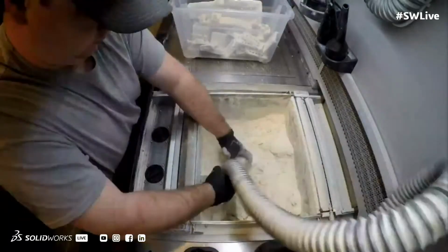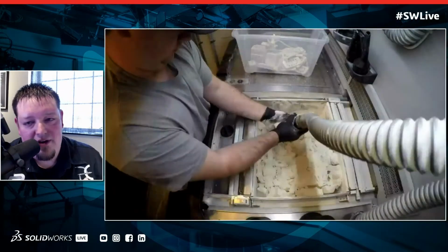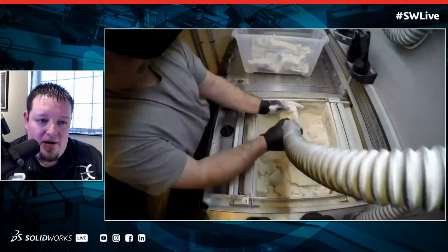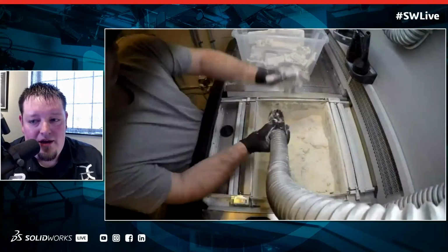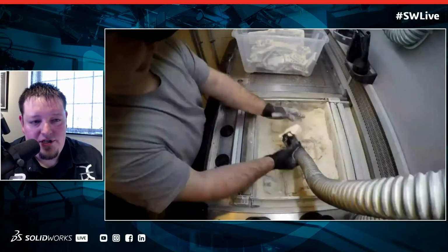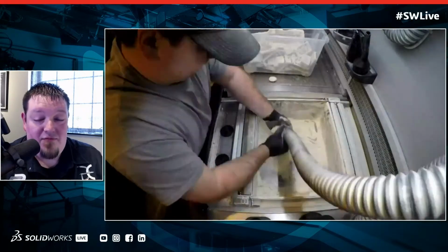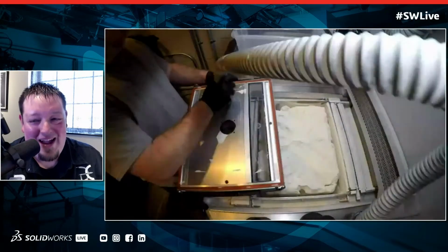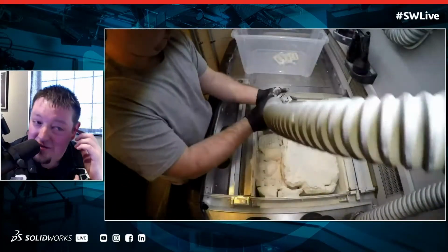Very cool. One of the things you mentioned, Paul, is the cooling period. You explained to me when we spoke earlier that one of the interesting things about MJF is temperature. It gets so hot that you leave it in there to let it temper to keep it from warping, like all the powder. Explain that. Yeah, so when you're printing, you're up north of 390 degrees Fahrenheit inside that machine, and you're putting a lot of heat into these parts. If you were to just print them and pull them out of the machine and unpack them immediately, first off, you'd need fire-resistant gloves because you're going to burn your hands badly. But then your parts are going to warp and twist and move all over the place.